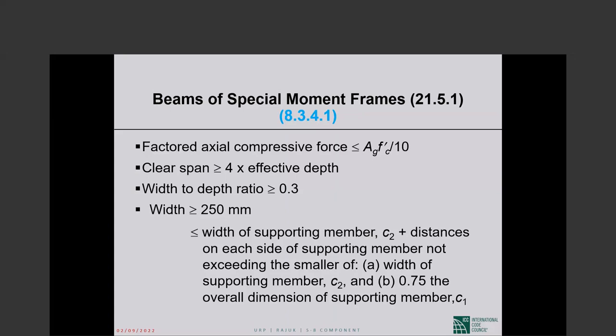You probably have the slab and no beam sticking out. So in that case, the slenderness may not be a problem. So what I will say is that if you don't count on those missing beams as part of your seismic force resisting system, you should be okay. This is a general answer without looking at exactly what you have in mind.